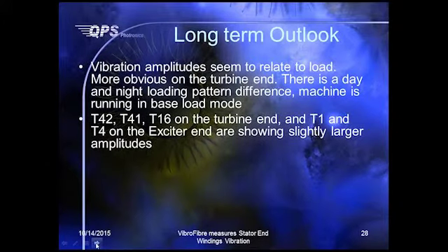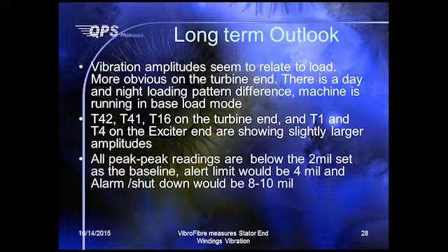Our conclusion is that vibration amplitude seems to be reasonable, and it is clearly dependent on load. From the technical specification that is being prepared, we understand that it is important to relate this vibration with, for example, temperature and also load, and operating parameters such as stator current.